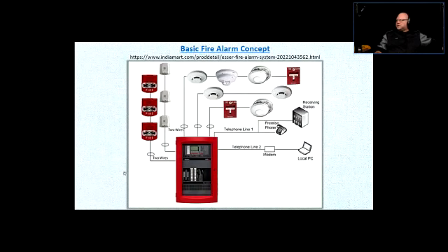So the basic parts of that would be the main panel, and you would have zones in there as well, which would be the contact points. They're organized slightly different than the security alarm. In the security alarm, the zone is looking for a closed loop. It's looking for a zero resistance. It's looking for a dead short, okay, to be at rest. And we'll talk about that a couple of slides down the road here.